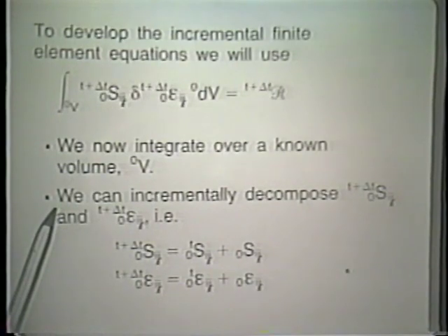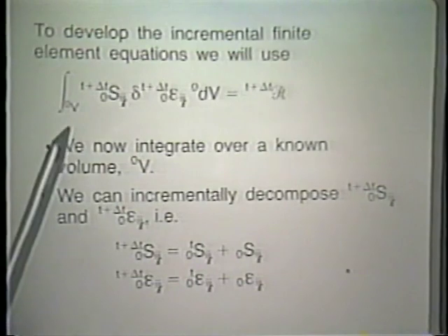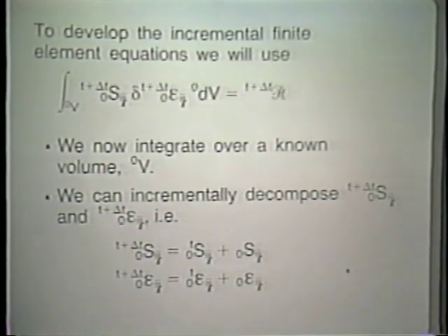These two items make it possible for us to work very well with the principle of virtual work in this particular form. Before developing, however, the incremental continuum mechanics equations, I'd like to discuss with you now some important kinematic relationships that we use in general nonlinear analysis. The second Piola-Kirchhoff stress and Green-Lagrange strains have some very interesting properties that I'd like to share with you in a discussion.